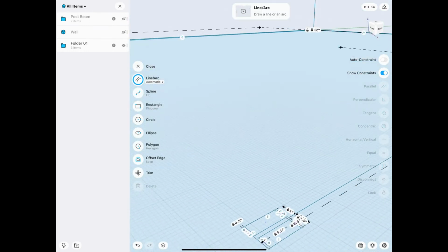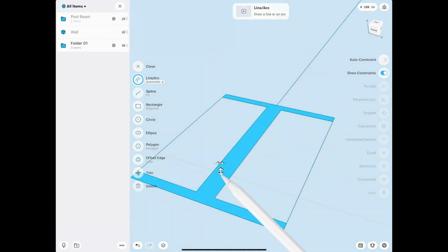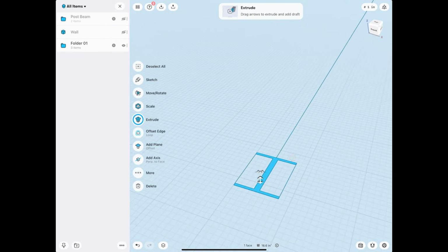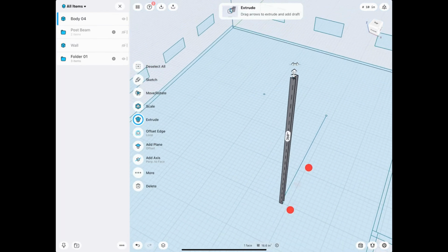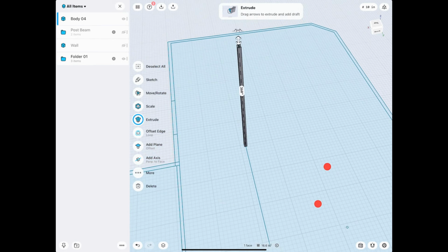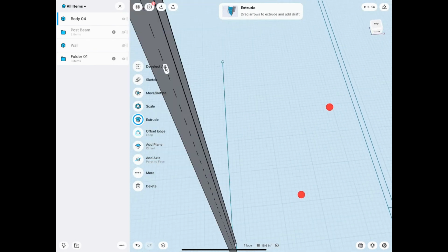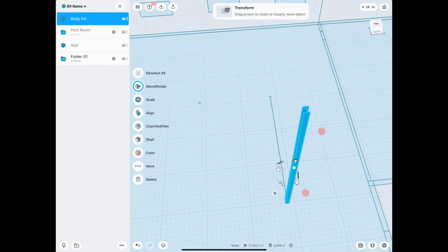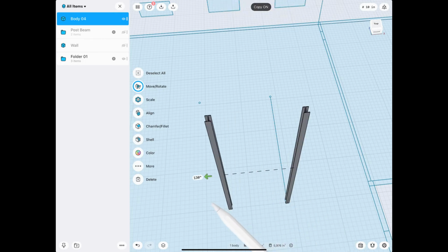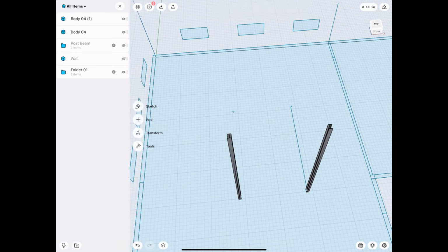So you saw how I drew a rectangle to then draw in the geometry for my I-beam. And this actually now I can extrude 160 up. There. Very good. I know the distance between the two rings is 200. So let's select this, there, make a copy, and bring this over. 200. Nice.